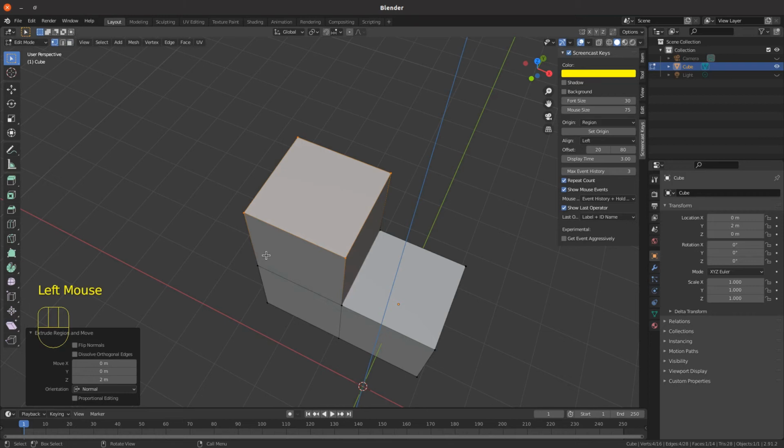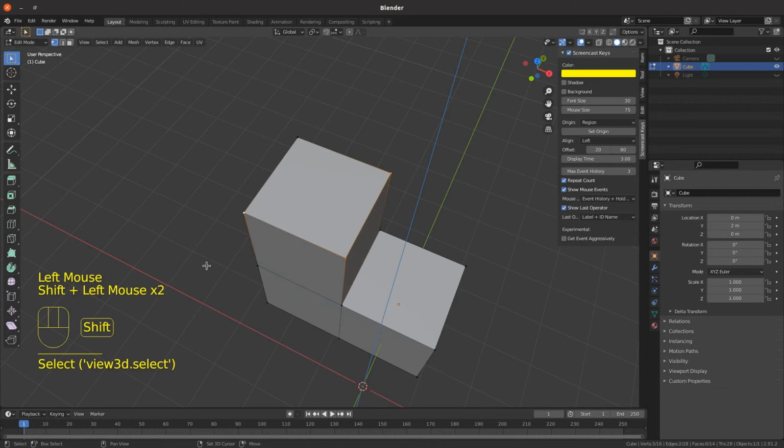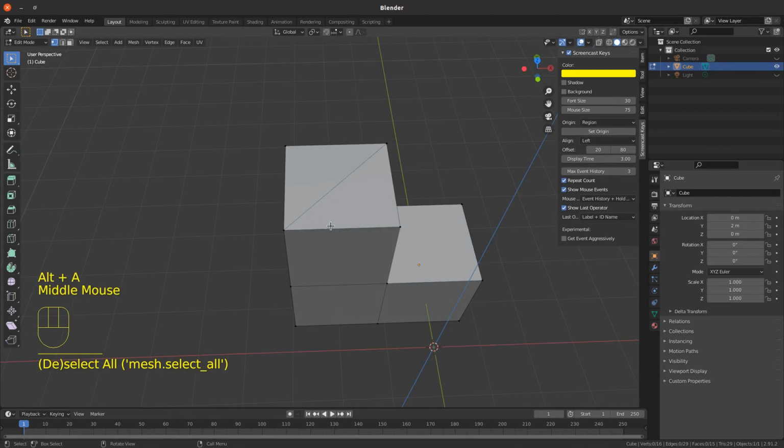But there is a situation that sometimes happens, and that is where you've got one face sitting on top of another. So if I added a face now with 3 vertices selected and then deselected everything, you could assume that that top face is made up of 2 triangles rather than one quad. But what's happened is you've got a square face sitting underneath or on top of, or exactly the same plane as a triangular face. This again can cause shading errors.